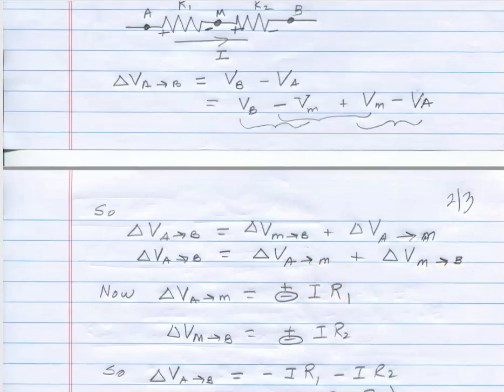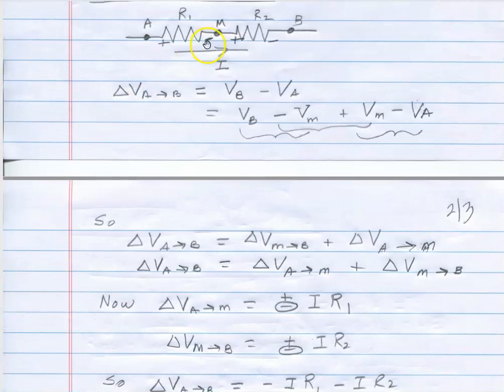Well, using what we know about the resistors, if I have an assigned current flow in this direction, current always flows from plus to minus, and so this side's the highest side of resistor R1, and this side's the lowest potential side. Likewise here, current flows through resistor R2 from high to low. So once I have the direction of current, I can assign the polarity, the high potential and low potential sides of that.